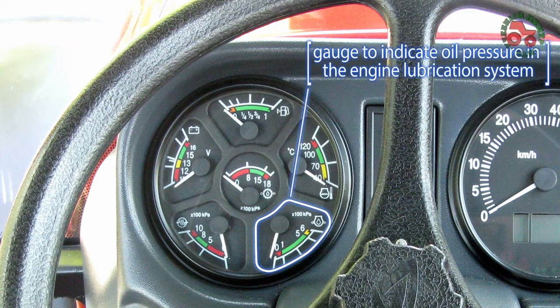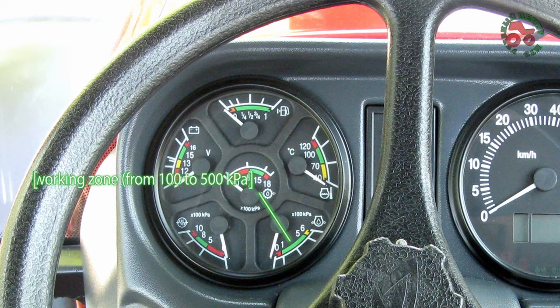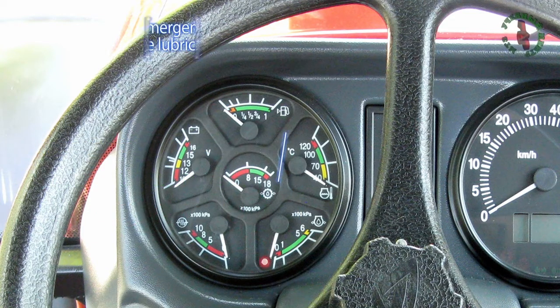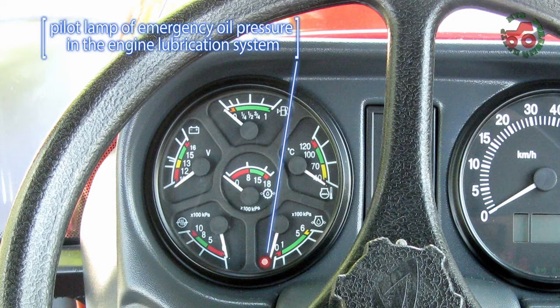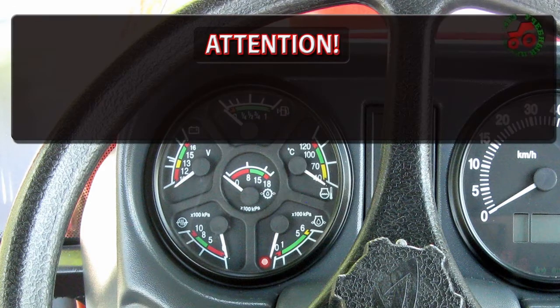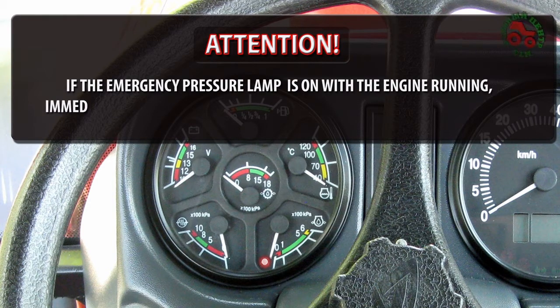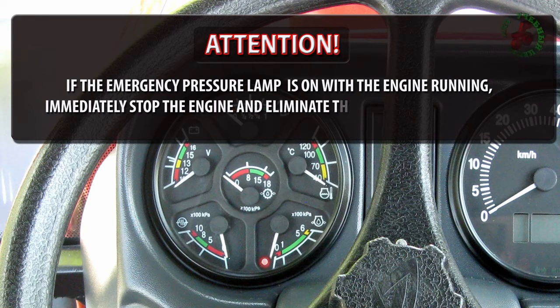Gauge to indicate oil pressure in the engine lubrication system. The scale of this gauge has 3 zones: working and 2 emergency zones. Pilot lamp of emergency oil pressure in the engine lubrication system lights up at pressure reduction less than 100 kilopascals. If the emergency pressure lamp is on with the engine running, immediately stop the engine and eliminate the failure.